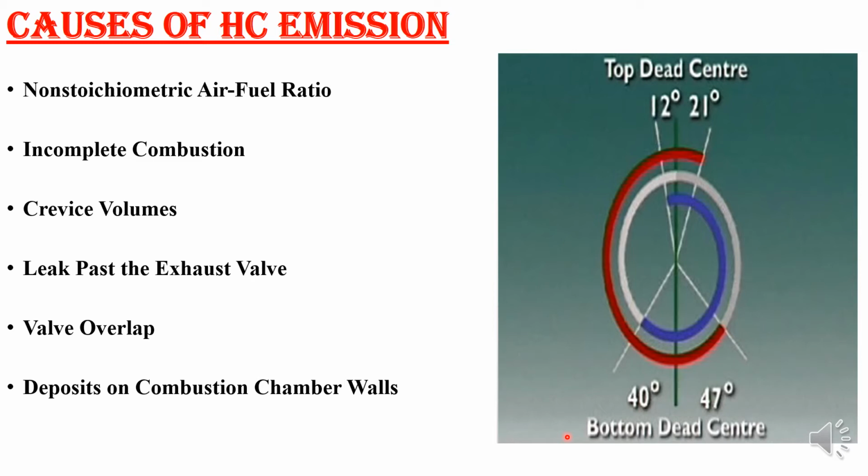So this problem is greater in engines with a higher compression ratio, due to the high pressure this engine can generate. More gas absorption occurs as pressure goes up. Clean combustion chamber valves with minimum deposit will reduce the HC emission in the exhaust. Most gasoline blends include additives to reduce deposit buildup in the engine.